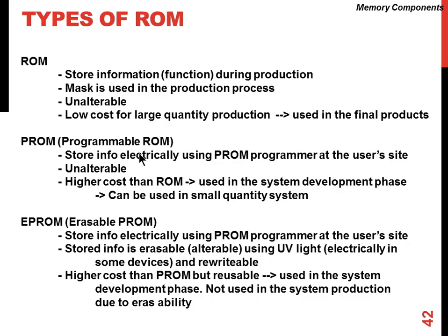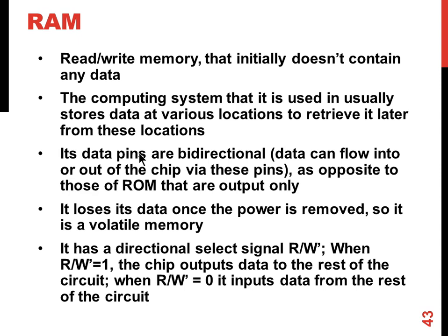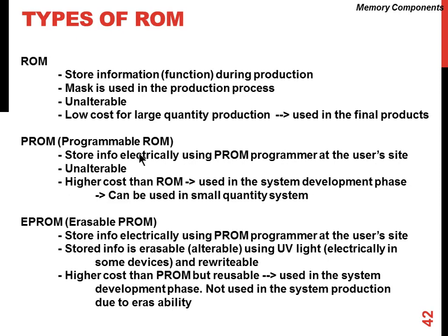Again, ROM has similar input lines. The ports are as in the RAM. The only thing we don't have is the write port or the write operation. We can only read from it. There are various kinds of read-only memories: a regular ROM, programmable ROM, erasable programmable ROM, or EEPROMs as we call them, which is electrically erasable. So most of the ROMs nowadays are EEPROMs, which can be electrically erased and reprogrammed to be used again, to be read again multiple times. Various kinds of ROMs are available.